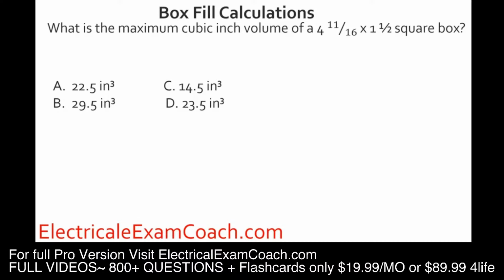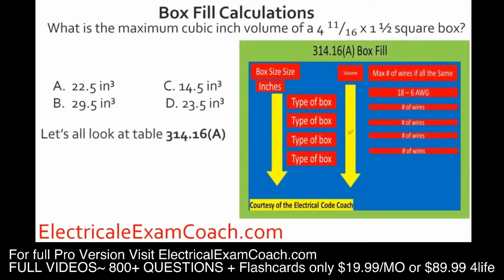What is the maximum cubic inch volume for a 4 11/16 by 1.5 inch square box? We're going to use the same process. We head to our table, go to that volume column, come down and find our correct type of box, and we're going to find that it's 29.5 cubic inches available area to fill.